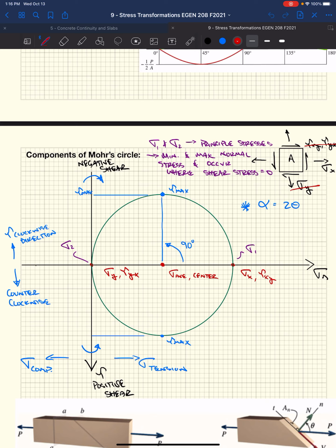So as I mentioned, we have a y-axis, which is our shear stress, okay? Our counterclockwise is in the bottom portion of our diagram, right? The positive side, the negative side, which happens to be the top of this diagram, thanks to Mohr, okay? Whatever shear stress is in the clockwise direction, that gets plotted up here. We have normal stress, which is positive to the right? So tension is on the positive axis in the x-axis, negative side is compression. So we plot our points, we make our circle, and it allows us to develop what our maximum stresses are in our element, right?